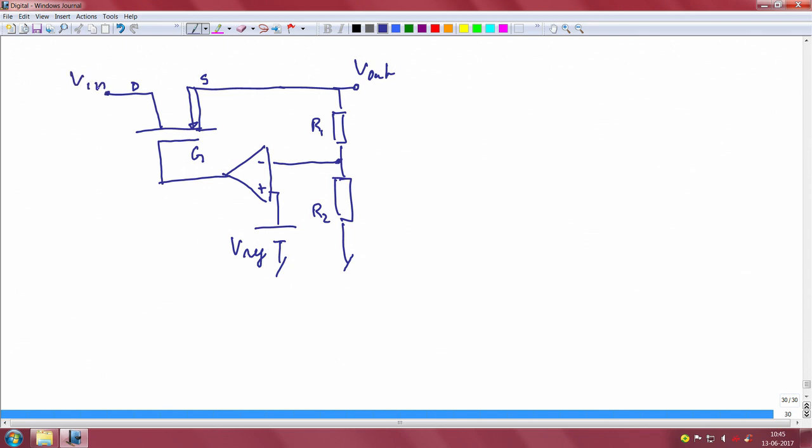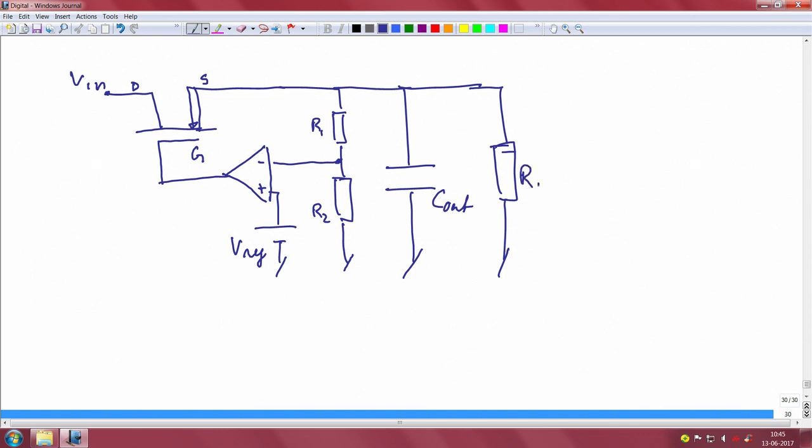V in, and this is Vref, and you can see this is quite simple to do. Obviously, you can't take the V out without looking for the stability, without adding the stability capacitor, which is very critical, right, and then you have the load. This is RL, this is C out. I also mentioned to you that we need an input capacitor, and that is C in.